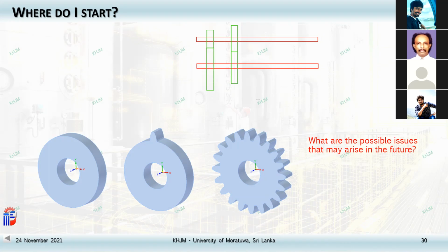And then I will take a copy of that and create a gear pair, a mesh, and show with a small animation how you're going to maintain and check that. Then you will realize that you don't need the gear teeth in order to make a gear mesh. You can define the gear ratio and then the solid will automatically animate that. So next week our discussion would be that.